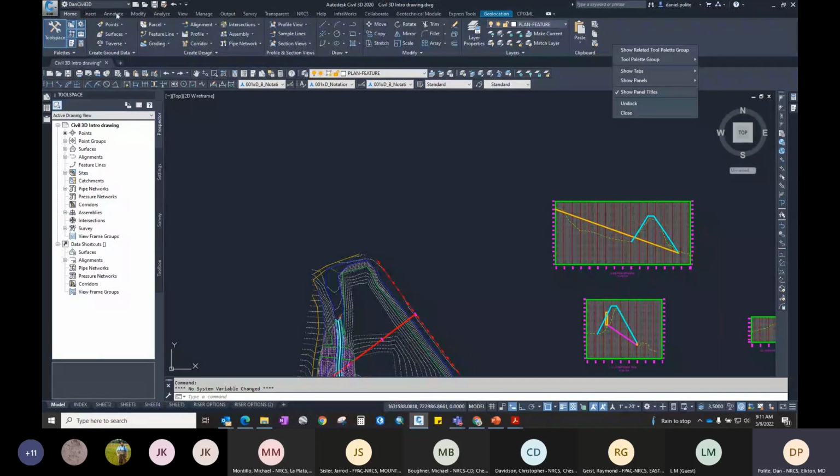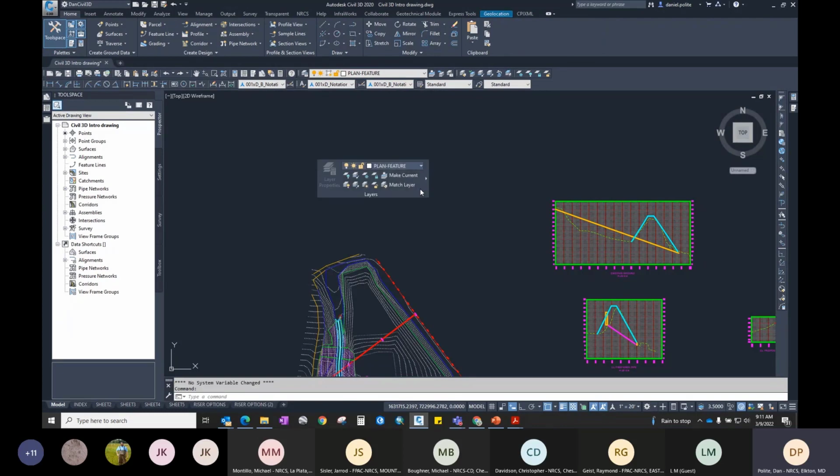Also, if you notice up here in the menu, you'll have different tabs again. But if you go into your CUI, you can adjust that too. If you don't want to see something specifically in there, you can go to your CUI and change that. You can also take the ribbon itself, click and drag it off of the panel itself, and it can be a floating tab. And on the right, you can toggle the orientation, so how you want it to look.